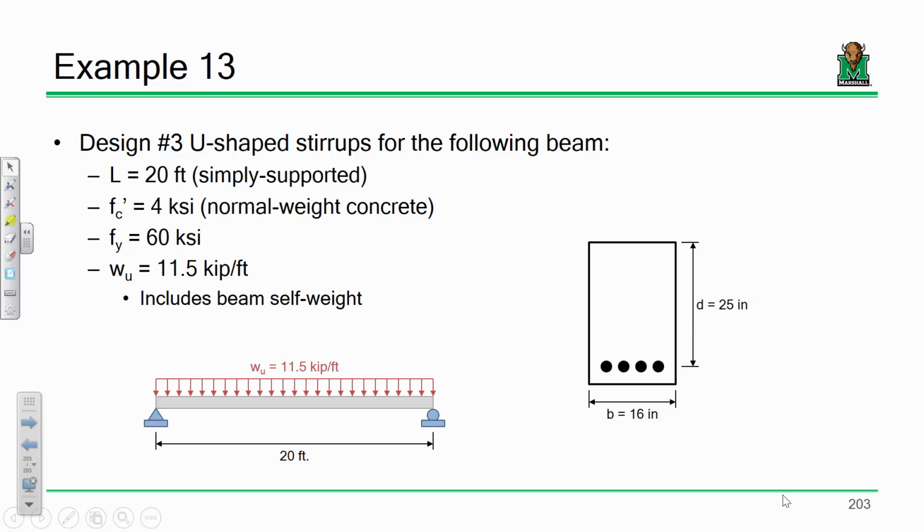Like we have a shear diagram that goes from x equals 0 to x equals 6 feet. But once we get past 6 feet, we have a new curve, right? A new line. So this shear diagram is not going to be defined by one equation. It's going to be defined by two. Now, regardless of which equation we're looking at, both of these lines share a common trait. Does anybody know what trait is common for both of those lines? The slope. What is the slope of those two lines?